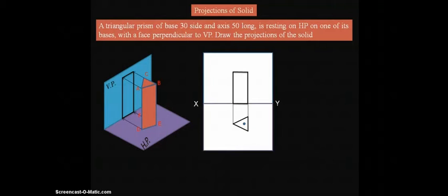By drawing those bisecting lines, we get the intersecting point that becomes the center point here. With reference to that you need to locate the axis of the prism. The axis of the prism you can easily locate with the help of the drafter you use for engineering drawing, by locating it exactly parallel to the sides and from the center point of the triangle.